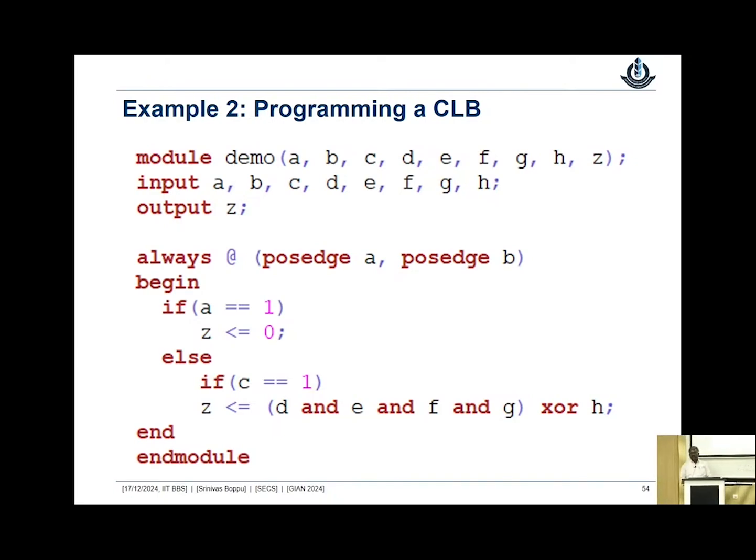So here, which is your clock pin? To that clock pin, which is going to connect it? B, very good. Which is the reset pin? A. Now you have it. So you can expect in your design there is a flip flop where the reset pin is connected to A and the clock pin is connected to B, and there is an enable pin. Let us assume there is a flip flop with enable. The enable pin is connected to what? Done. And now what goes to the D? This whole expression. Now you need to think of how we really implement this whole expression.